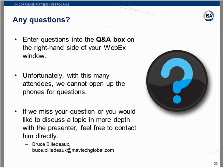If we're just doing a basic analysis, I use Wireshark. It's free and easy to use. But a lot of the tools that are built into your network switches that you already own, that are already on site, are usable, as are the vendor tools. I know Rockwell and Siemens both have some pretty good tools now for watching network traffic and determining if something's out of band.